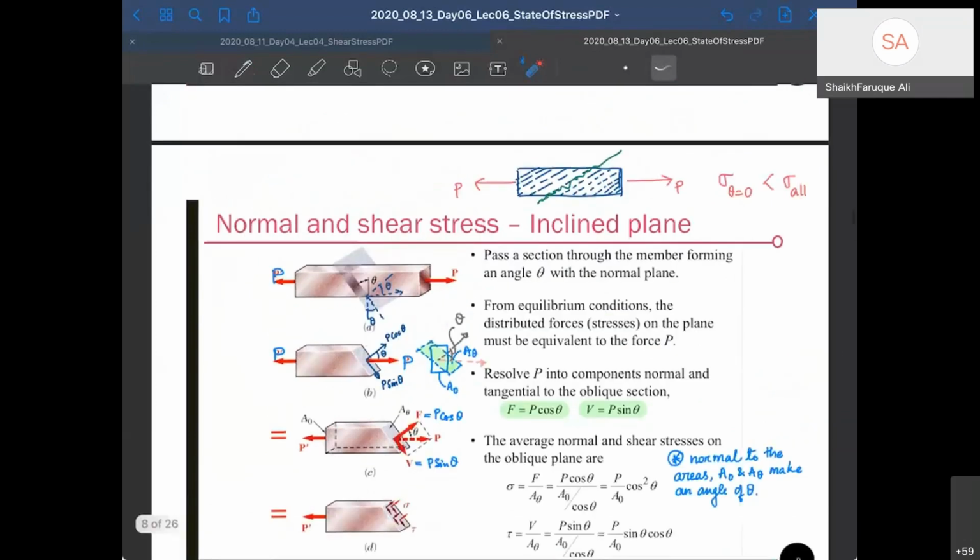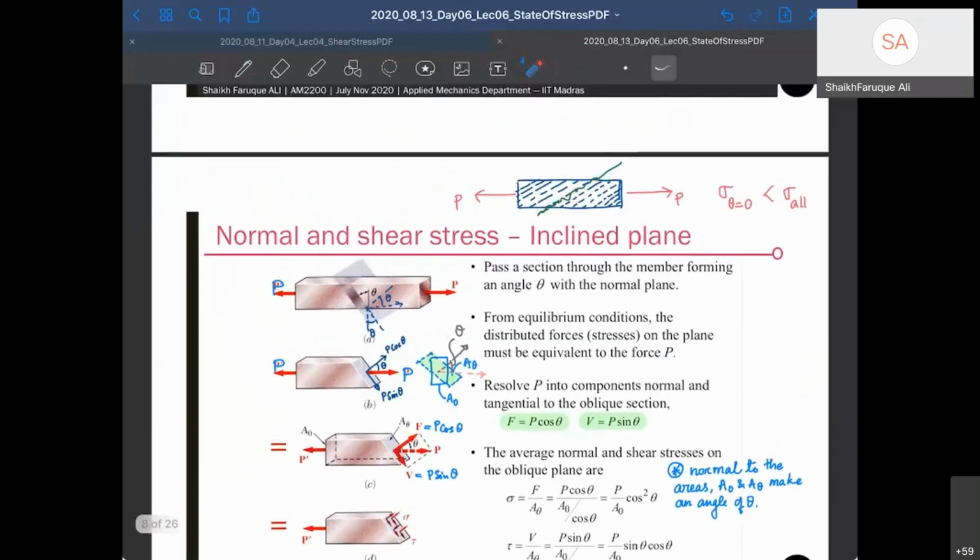And if there is a shear stress along this plane, you know that this plane is going to move in this direction and that plane is going to move in that direction, right? Because the fibers are aligned in this way, they can easily break away from each other, and they can move on in a direction, so it can fail in shear, which you did not check. Therefore, as an engineer, your objective will be to check every direction of the cutout plane, at which plane it can have maximum stress, and along that plane, you have to check sigma allowable and tau allowable.